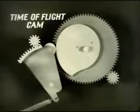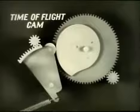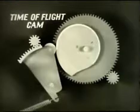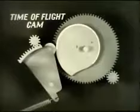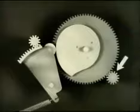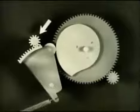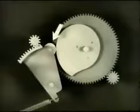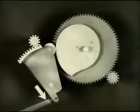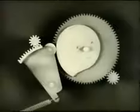This time of flight cam is an example of a flat ballistic cam. The working surface is the outside contour of this part. The input is range. The output, time of flight. This is a sector-type follower, held in contact with the cam by a spring. You can see how the cam turns the output gear.